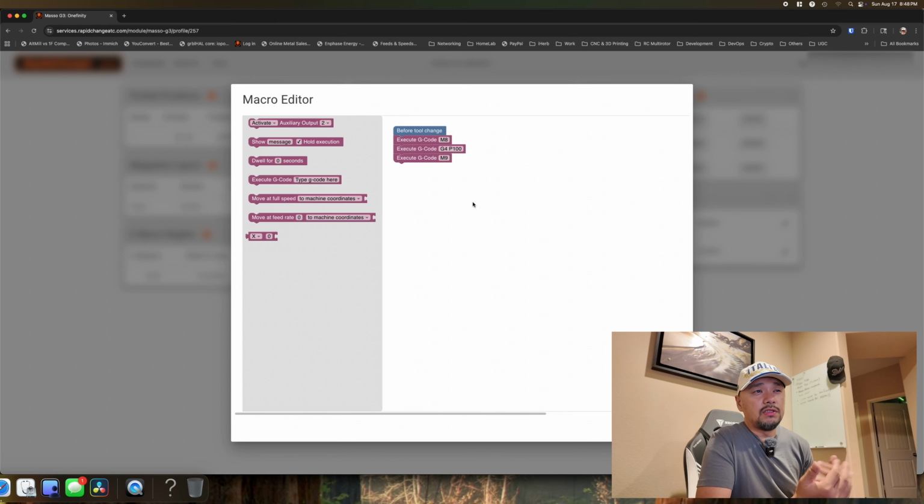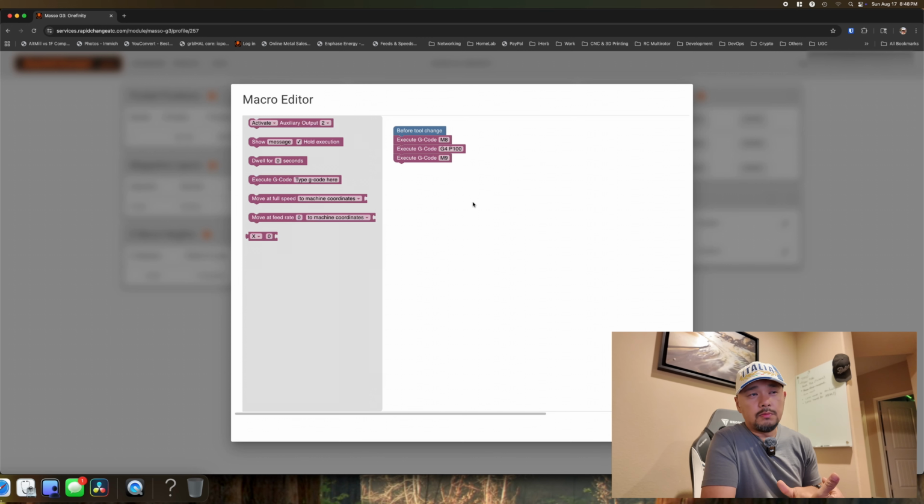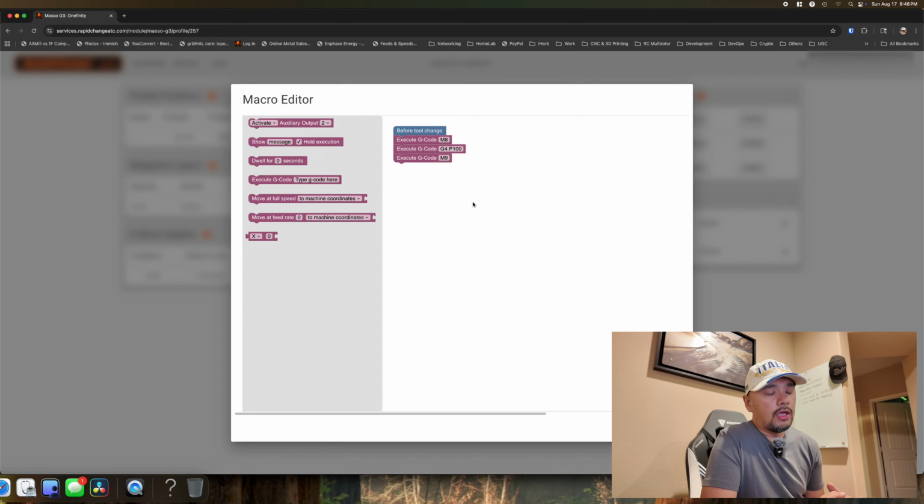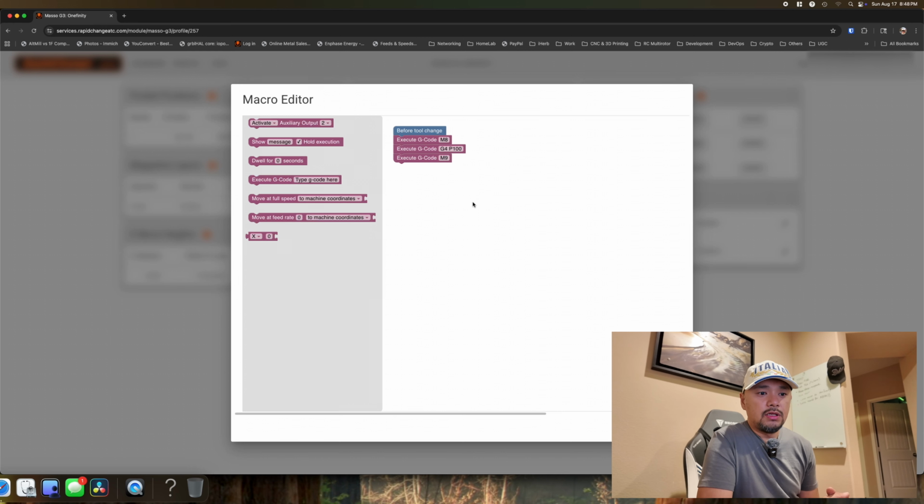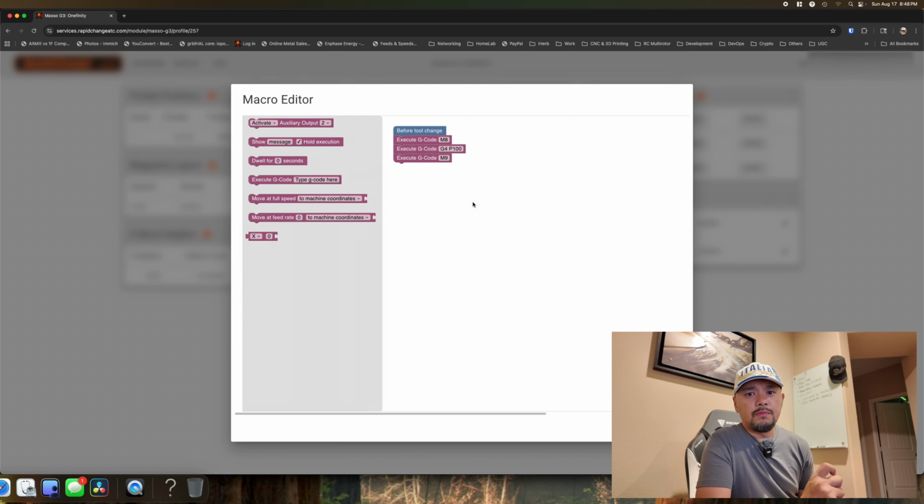Why can't you just M8 and then M9 immediately? Why do we need a delay? Okay, the explanation is, when I programmed the microcontroller of the AutoDustBoot, during my testing, on some of the controllers I measured this coolant flood signal. Sometimes it's susceptible to EMI, so there's a voltage spike that my microcontroller will pick up. It's like a very fast on-off signal because there's a back voltage signal.